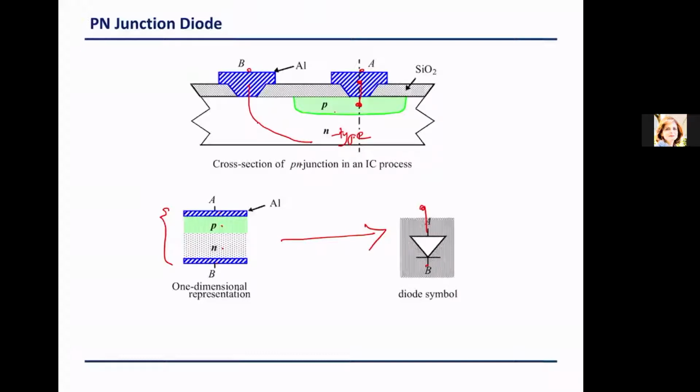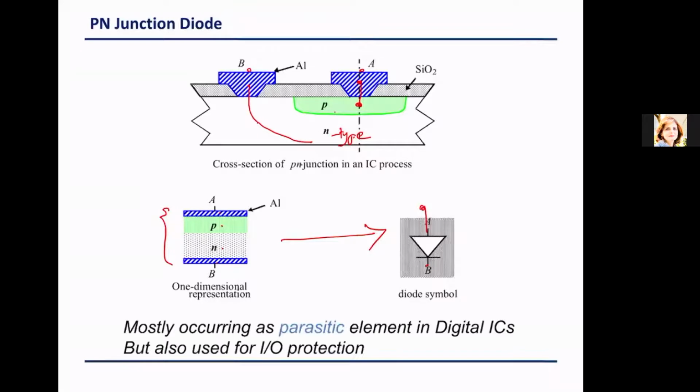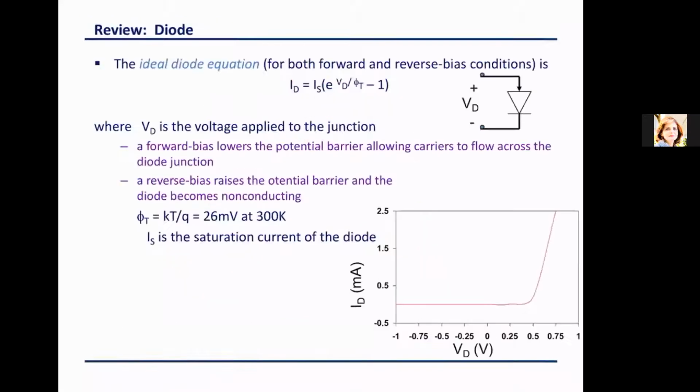And from this symbol, we derived the model in the previous classes, but we need to know that a basic model will have some parasitics in addition to the simple functionality. Of course we're not going to use this equation, but I'm just trying to tell you that when we studied this, we said that the I diode is equal to IS e to the VD over N VT, right?